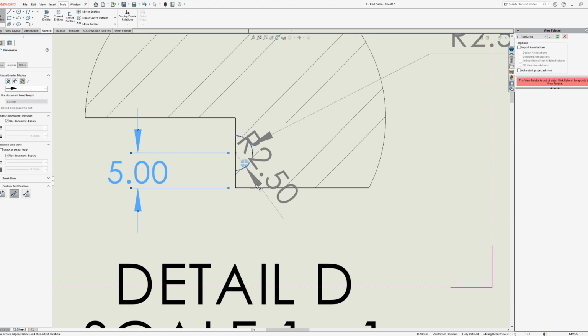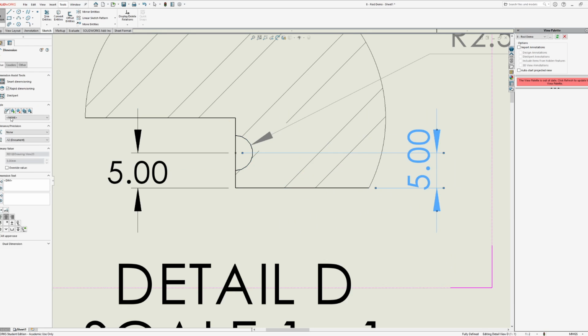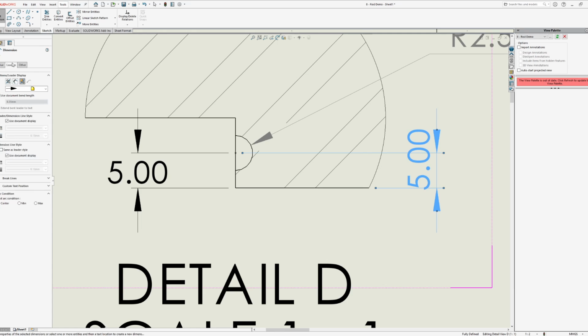There are some details that I kind of glossed over when we were going over Smart Dimension. If I just place this here, where is it? Here it is. So arc conditions. Usually if you're smart dimensioning either an arc or an arc with regard to some other reference point, you can choose specific details about that smart dimension.